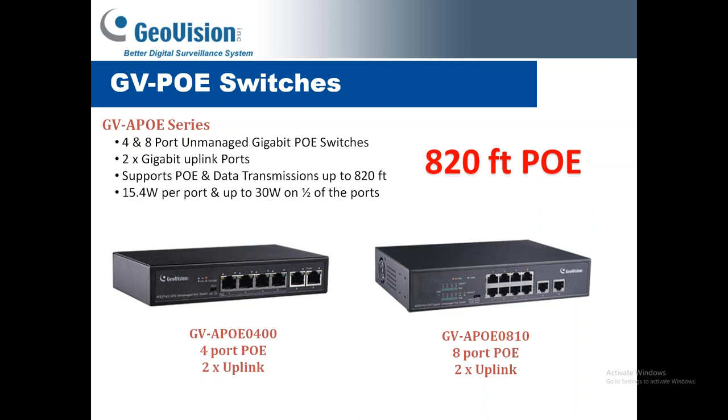A newer series of switches that came out last fall, this is called the APoE series. We currently offer these in a 4 and an 8 port. These are unmanaged. And the big benefit on these is they have a feature called CCTV mode, which allows you to go up to 820 feet of PoE and data transmission.